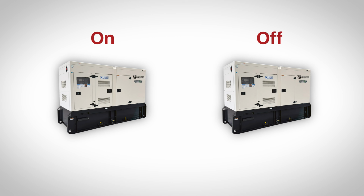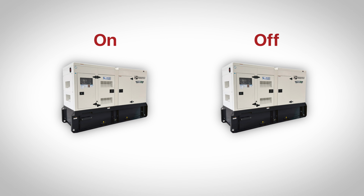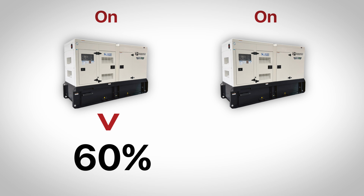Examples of how you might use this in the real world, I can take experience from the switchgear company I worked for. We would be controlling generators, and sometimes you would have multiple generators, and you would want to only run one generator if you didn't need to run the other ones. You had two generators, and you only wanted to run one unless the load on that generator got above 60%. So you could use a comparison instruction to compare that load on the generator that's coming in through an analog input, for example. Obviously, there's 1,000 different ways you can use these comparison instructions, but they're very valuable.